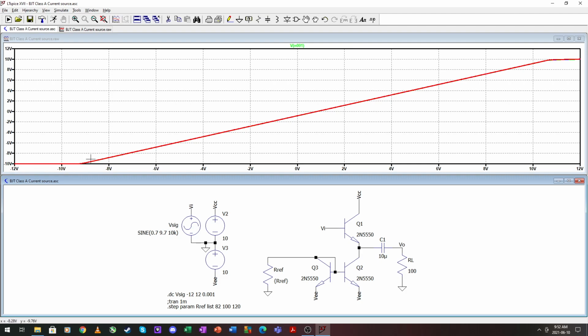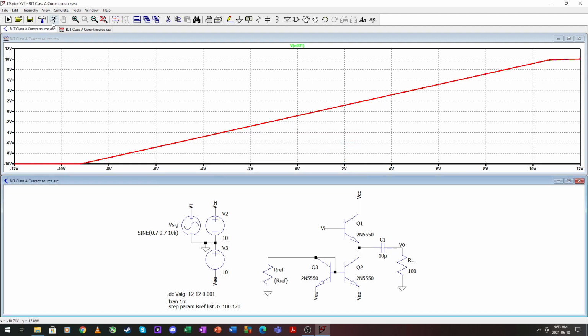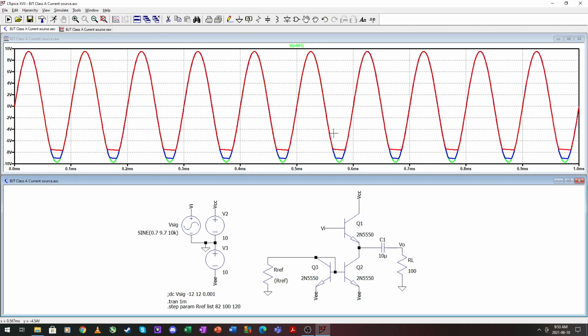Also note that due to the capacitor, all this loading effects of the different reference resistors disappeared on the low side here. Okay, so having this cap here makes this very inaccurate. Okay, so transient running, see that is still there. It didn't disappear due to what we did.